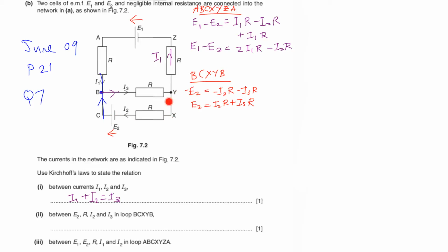Now we will travel through these two resistors. So for this resistor, remember we are traveling this way, from C to X, but is your current the same or opposite, Abigail? Direction of travel and current, same or opposite? So is your PD positive or negative? What is the formula for PD of this? I1, what are you using here? So what is Abigail's answer? Positive or negative? Negative I2 R. What about this part? What is the PD across this top R? Positive or negative? Negative, because the direction of current is to the right, but travel is to the left.